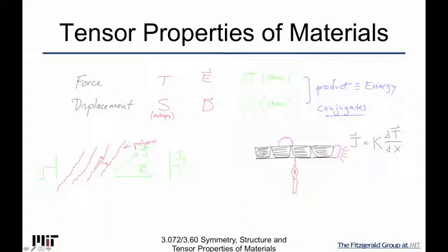And that's because these little layers of graphite, right, the thermal conductivity J in this direction is super high, where of course across this, where the bonding is very weak, it's very difficult to transmit phonons, and it's very low.